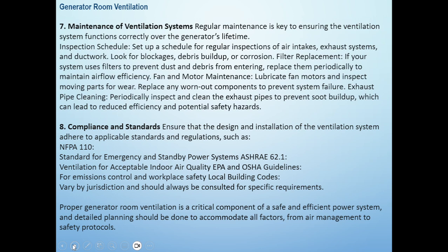Next, compliance and standards. Ensure that the design and installation of the ventilation system adhere to applicable standards and regulations, such as NFPA 110, standard for emergency and standby power systems, as per ASHRAE 62.1, ventilation for acceptable indoor air quality, and EPA and OSHA guidelines for emission control and workplace safety.